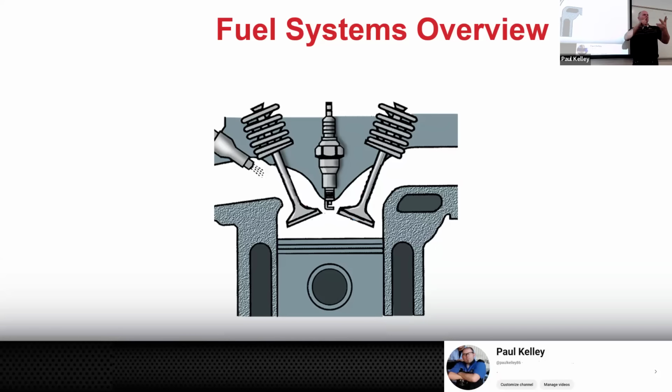Maybe it's got no spark, maybe it's got no fuel, maybe it's got no compression, right? So if you're looking at those three, we're now on the third subject. Once you get this one, you should be able to diagnose all those crank no starts, no problem. If the fuel pump's no good, you've got no fuel to any cylinder, and you're going to have a no start. But what if it's a little more complicated?